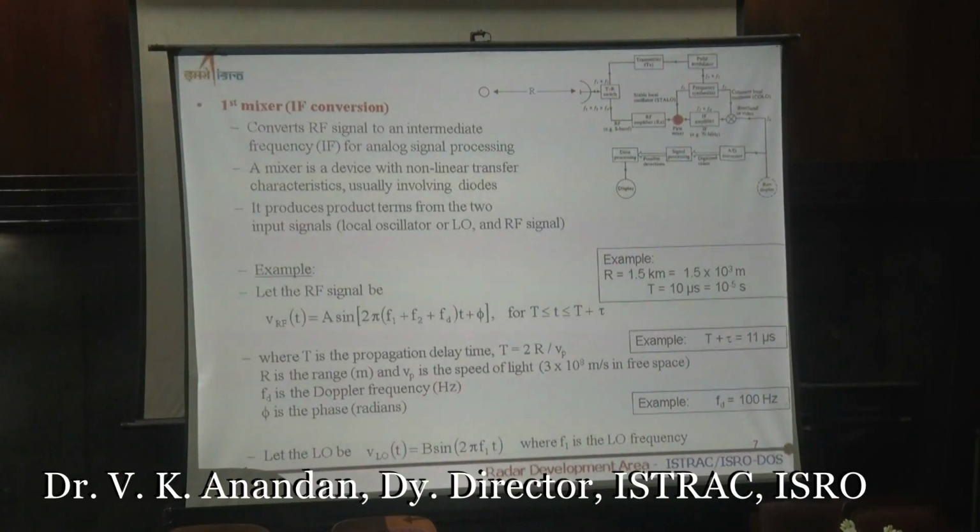You are sending RF signals, which are phase shifted, and you get back the frequencies F1 and F2 that you transmitted, along with some component which is a characteristic shift of the atmosphere. The phase also gets changed along the transmit path. These are all important characteristics. When an electromagnetic signal travels, amplitude and phase are the most important points to look at when it comes back.